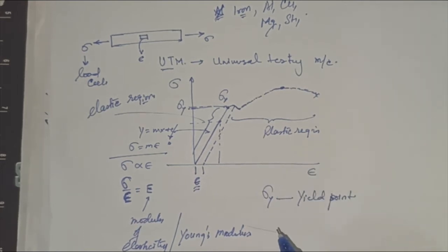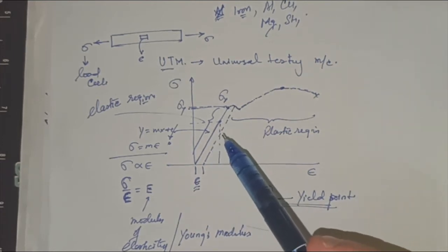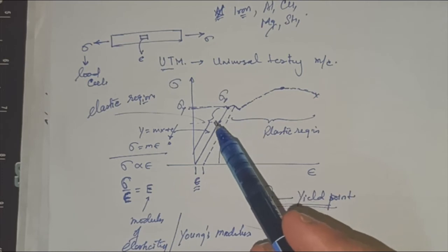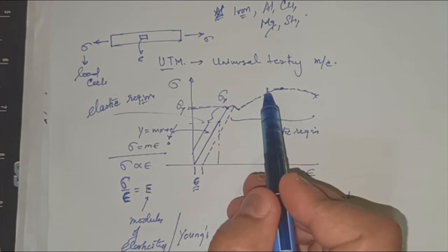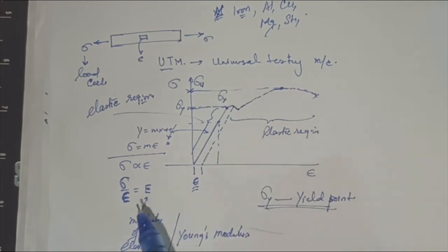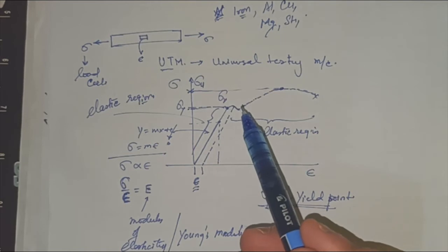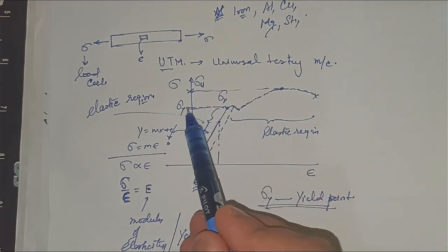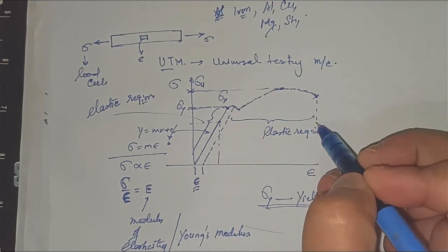So that's why most of the failure theories and failure conditions consider the material to be failed at the yield location. But usually it doesn't happen, and theoretically, the material also has one more strengthened point, which is known as ultimate strength, sigma u. This is the ultimate strength of the material. This is only 10 to 15% or some 20% higher than the yield point, and beyond which the material actually fails at this location.